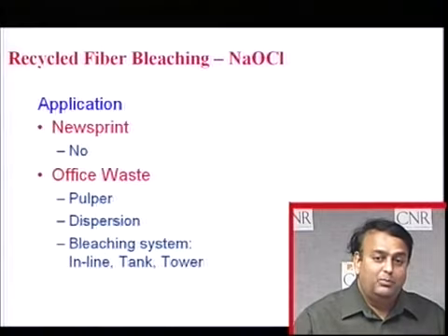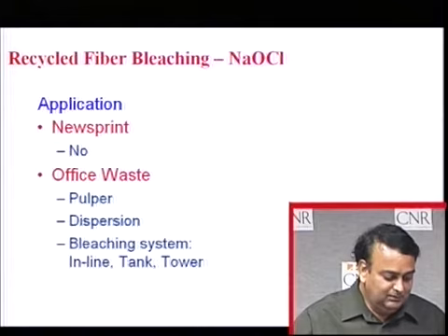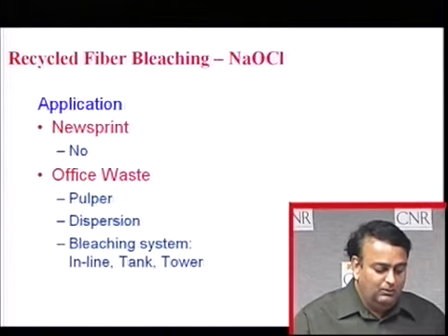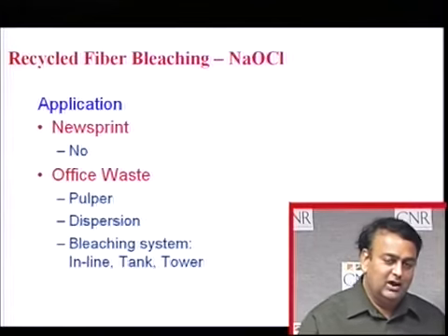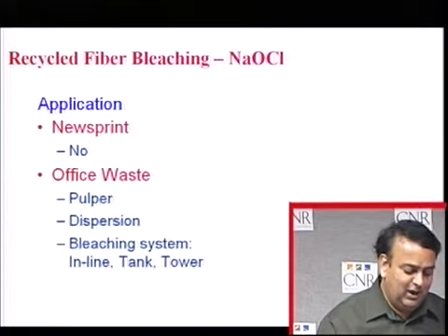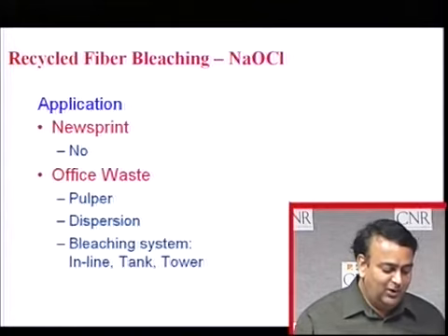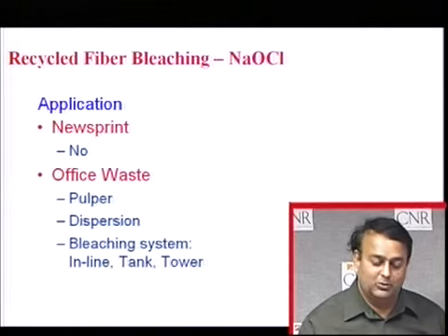It's very popular for bleaching office waste. You can do it in the pulper. In the pulper you can add hypochlorite, or in the dispersion where you have nice consistency, you can add hypochlorite there. Most popular is inline or any tank or tower bleaching with sodium hypochlorite.